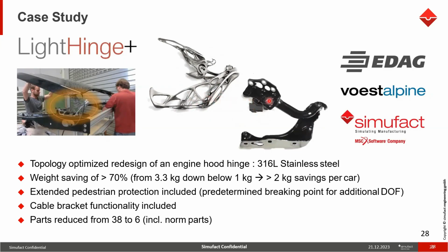Okay. So there are different topology optimization tools in the field of simulations, where we can get optimized designs like this. But you can get the optimized design, and whether it will perform or not, that is another question. Whether we can manufacture it, first of all, we cannot manufacture these components in traditional ways. That is another challenge. So this is where we use additive manufacturing technologies to build parts like these, so that we can optimize the weight, as well as reduce the material utilization.